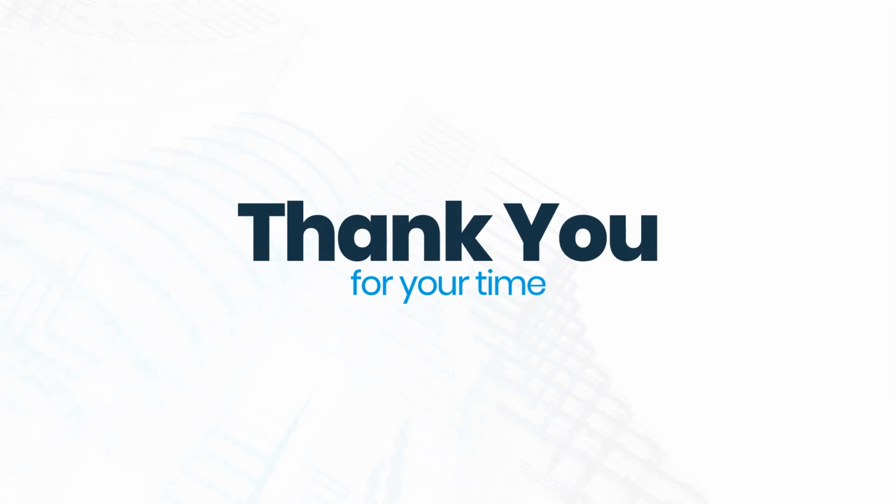Okay, what's a good workflow for updating Topo Surface from civil consultants after they've built the initial Topo Surface from their first Civil 3D file? Okay, again, I would say go ahead and link the file, and then draw it and then unload it after you have it, and then you can always turn it back on.